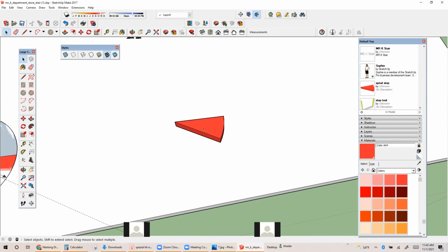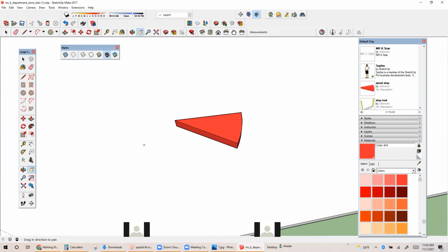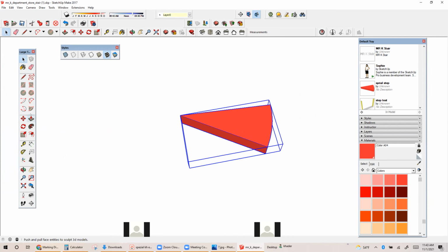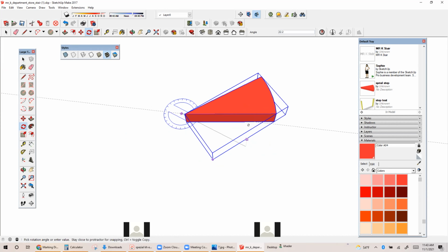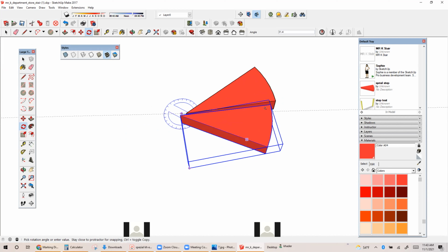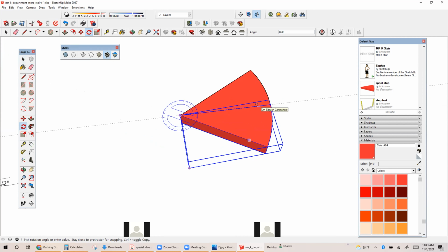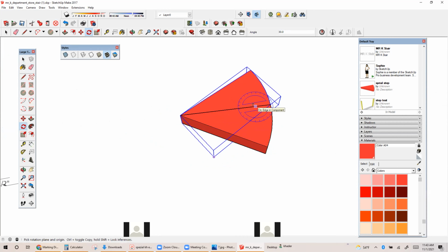So the next step. Rocco, you with me on this? Yes. Francisco, are you there? Yeah. Watch this. You select the step. Remember our friend rotate? I'll put the rotate in the blue direction. I press control while I'm rotating. I'll make a copy. Oh, I messed up. One more time. You select the item, rotate, you press control first. You click the beginning of the rotation and you drag it towards the end. And then you type 3 times 4 is 12, so 11x.